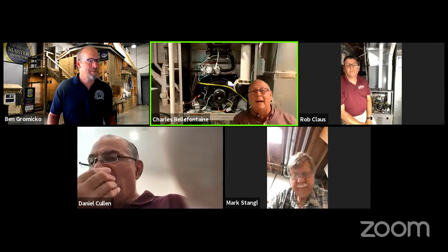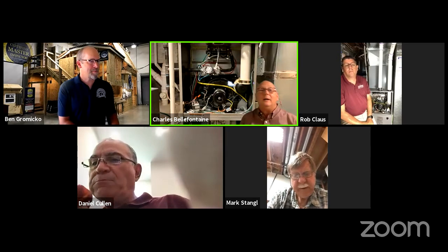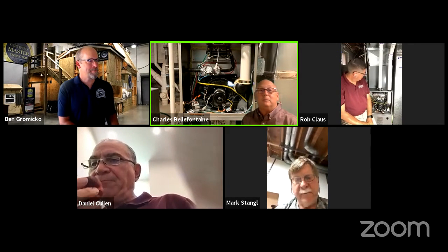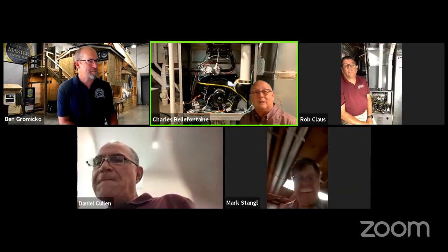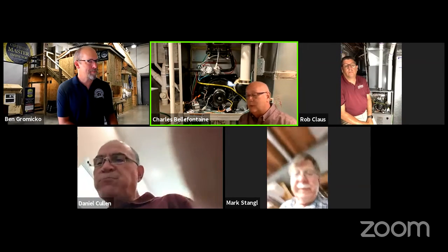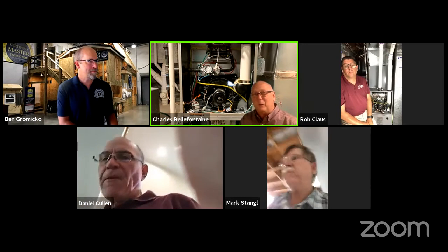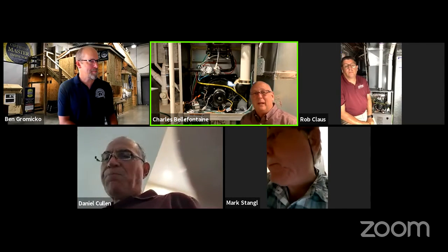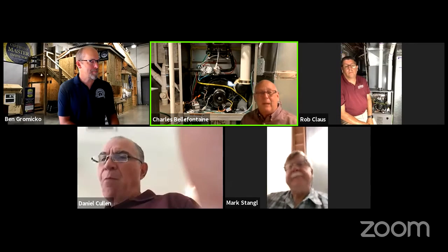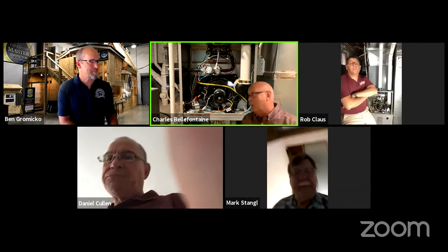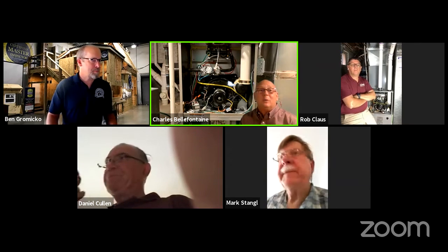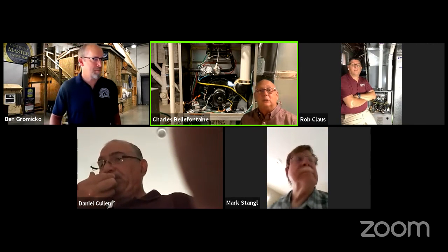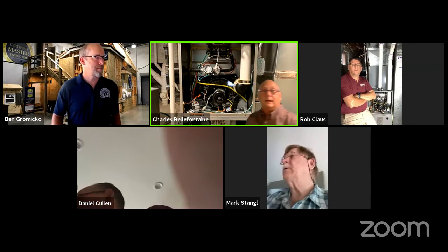Then we open up the top, and I have to put the blower door back on, otherwise the unit isn't going to run. For me, I'm kind of particular. I like people should know how all the different parts on these things work and the sequence of the startup. And as long as you know what it's supposed to do, when something's not right, you're going to be able to start diagnosing and figure out what's going on or what might be broken. I'm always one to want to know more. So the steps of operation and also the components that are in here, I think are important.